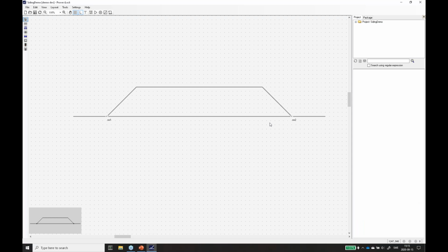Next step is to add these joints so that we can place signals. And then I will use a feature here called repeat new object, because I will place quite a few of these joints. I will just name them. These names are not maybe that important, but I will just give them a D for delimiter. Obviously you have to take care so that you don't try to create objects with the same names, because then it will complain. I will have to rename it later.